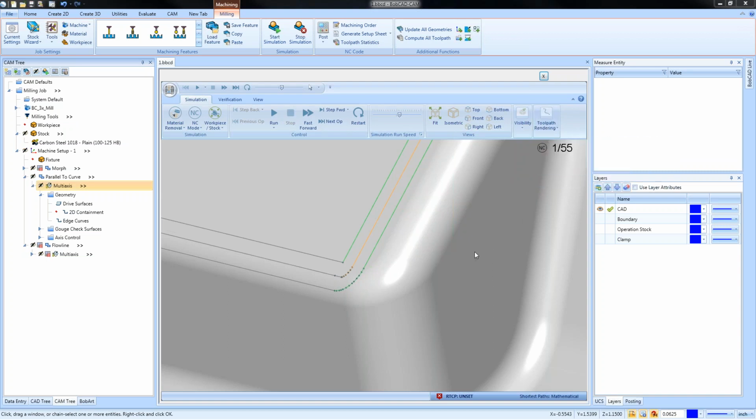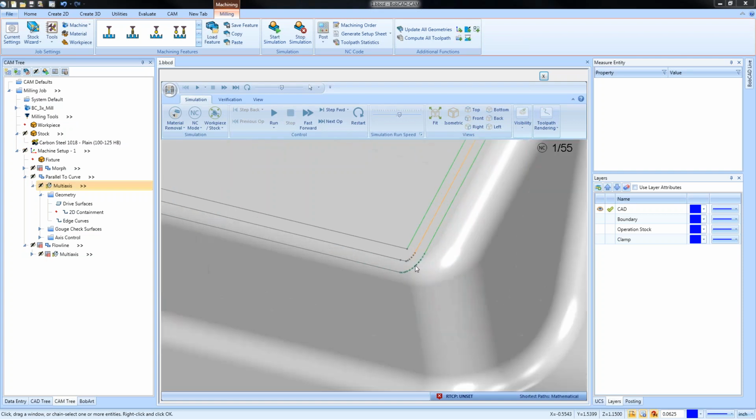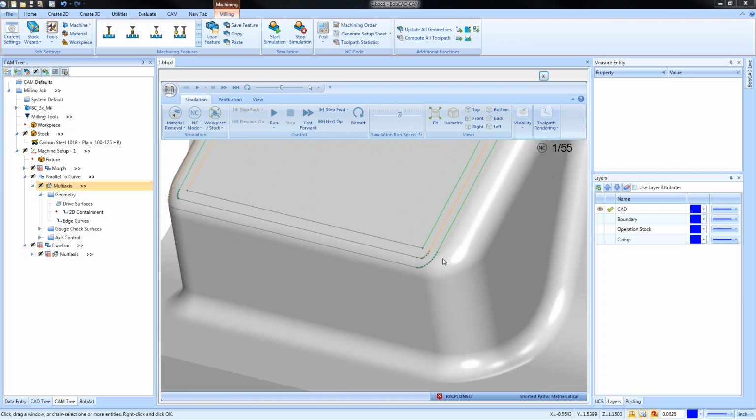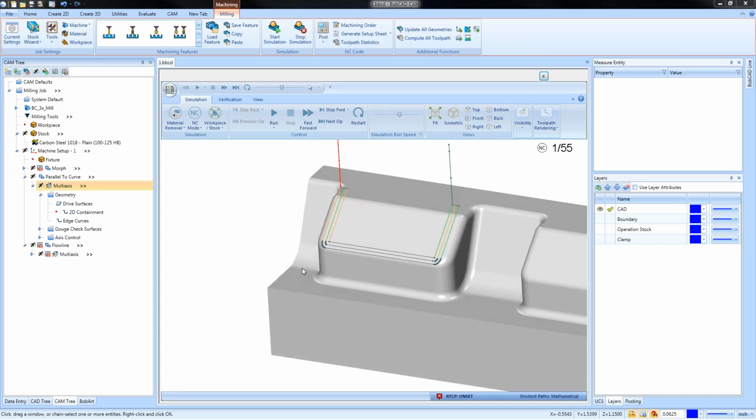So these are showing us the points that are making up the toolpath. The points would be the movements, right? So how many movements there are, how close they are together, this type of stuff. And when you're dealing with 3D machining and you're trying to get the best finishes, your point distribution becomes a topic of interest, and the control that you have over point distribution.